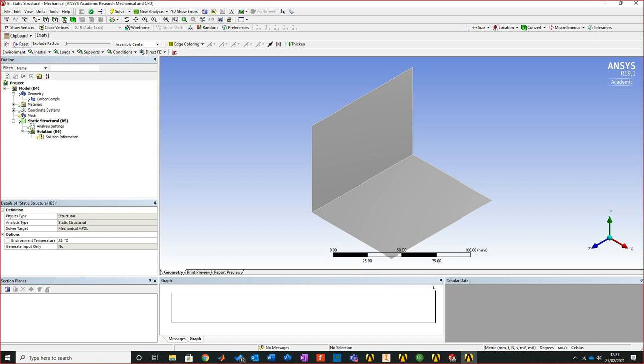Right, so when it comes in, what we'll do is we'll apply a similar type of scenario here. We'll fix it on this face here, and let's pull it apart and see what happens when we pull it apart using the 2500 newtons just on this simple layup. But what we'll do is we'll do 2 layers of carbon. We'll orientate them at 45 degrees apiece, and then we'll do a sandwich in the middle. Then we'll do 1 layer of carbon to sandwich to 1 layer of carbon. Then we've got a comparative between the two.